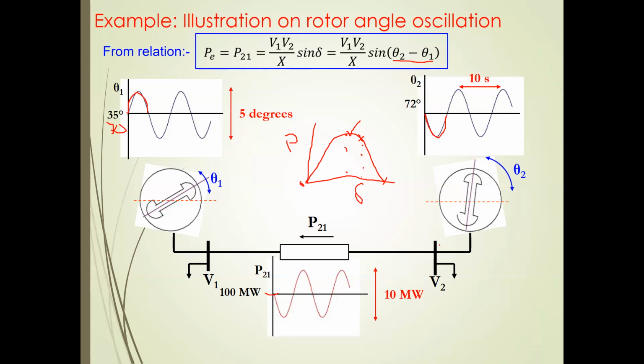But one thing I can say: I have shown it for one generator. This is a large generator, right? Let's say you have some more generators here. Since you have several generators connected to this bus, and you want the power flow in this direction, you can regulate the generator angles of all these generators to be the same value. That is possible. But the angles of this set of generators and the angles of this one have to be different if you want the power flow here.